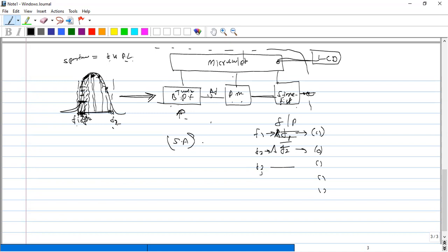Now in the storage, you have the frequency versus power. So you should code this microcontroller to plot this value on the LCD. So that is very simple. That is the spectrum analyzer. This technique is mainly used in many spectrum analyzers. This is one standard method to construct the spectrum analyzer.